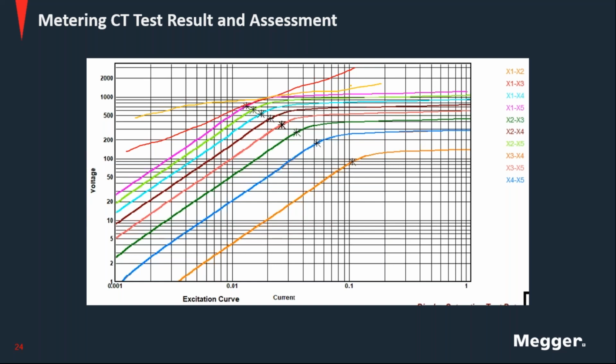For ANSI 30, that means using a line at 30 degrees and touching the curve. The difference is that the 45 is used for CTs with non-gapped cores, and the 30 is used for CTs with gapped cores. And how do we know if it's right?